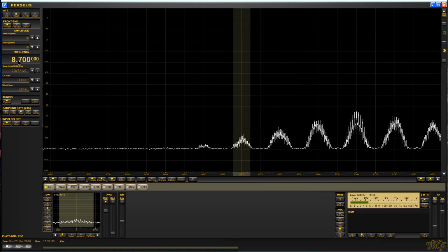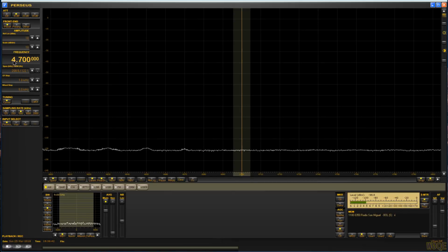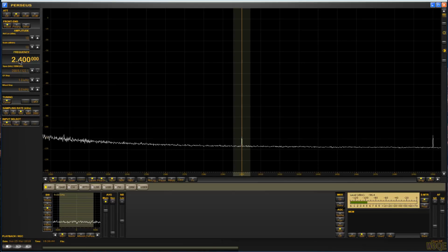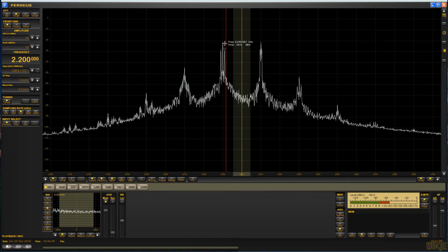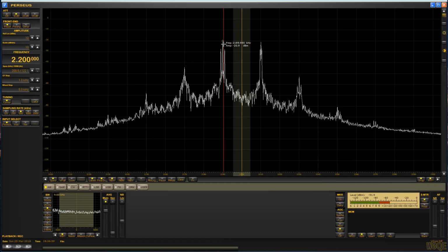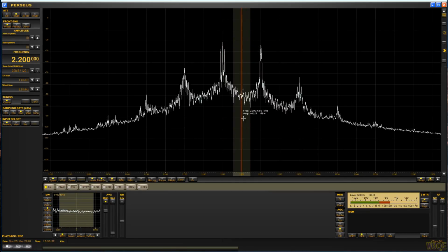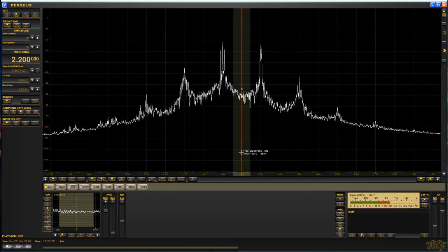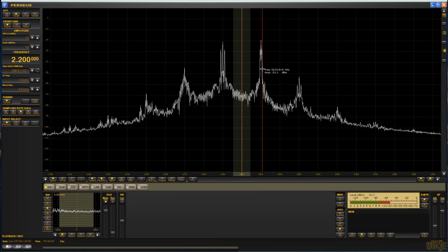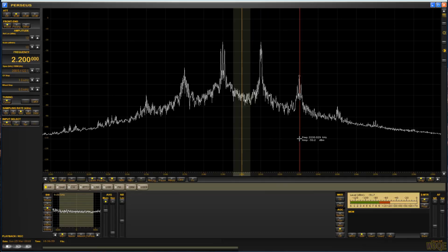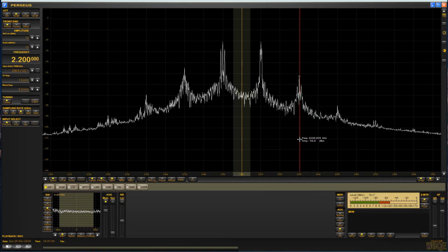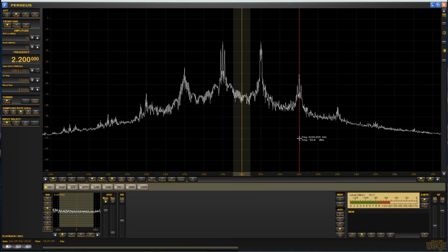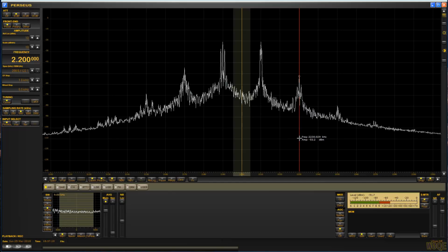But my original group right here were S9 plus 50, and this little SDR that I've got this hooked to shows this intermodulation distortion down, like in this range down here, 40 or 50 dB below this, when I combine the two in a nice manner with power combiners and attenuators on the output of both generators.